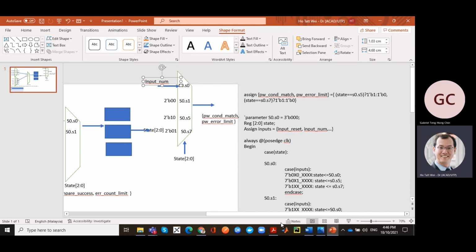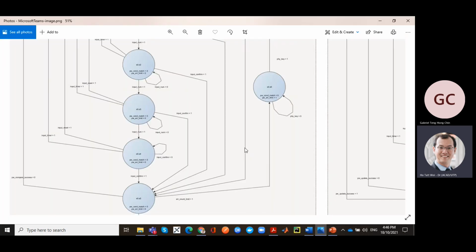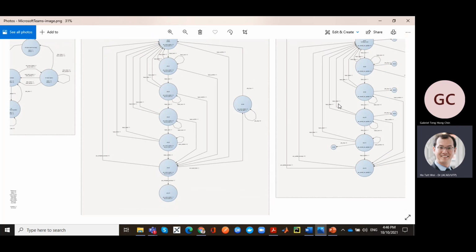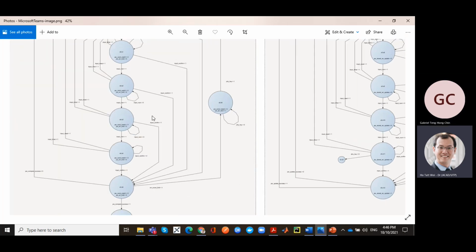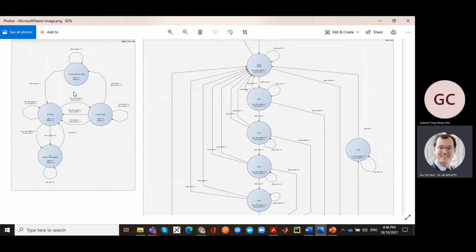So now, very crash course, you know how to encode one state machine. You can go ahead and design this, and you can go ahead and design this. The only difference is here, this is an output. The output will be one of the inputs to this state machine. They're pretty decoupled actually. That's the nice thing about this. It allows you to reason about it. So this is running. You can go ahead and design this, and then just the output there is the input to here. So you just have to make sure you have no kind of crazy circular logic.